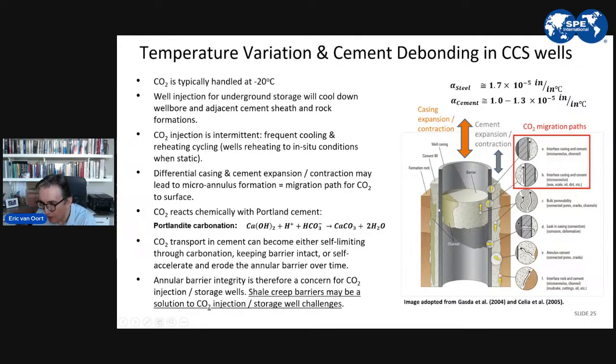That is a particular weak link. For those of you that are familiar with cement bonding to casing, cement bond strength is probably only about 100 to 200 psi. So that bond is easily sheared. And if you shear it, you will generate a microannulus between the cement and the casing.